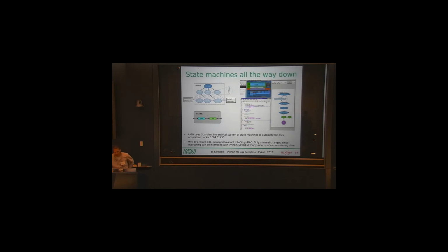The way we do that, and especially this log acquisition, is by using a system of state machines. It was something developed at LIGO. So it's a hierarchy of state machines. On top you have the master node, where you can really say from everything switched off to go to science mode, and in the ideal case, it's just one click of the button. And this top node then commands several other nodes which are running at a lower level.